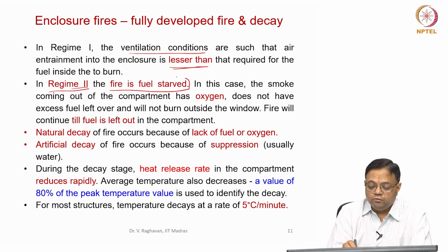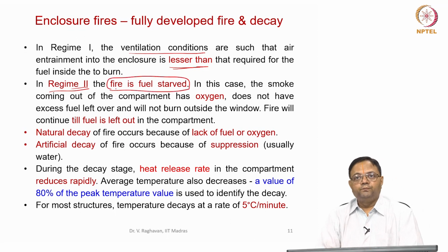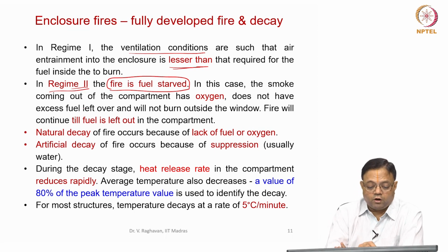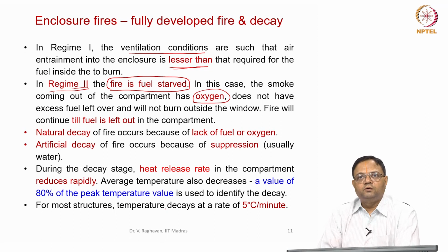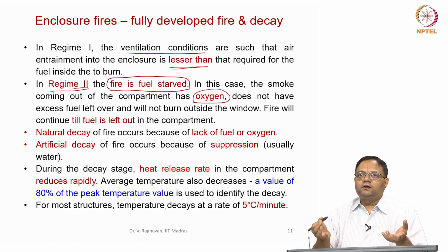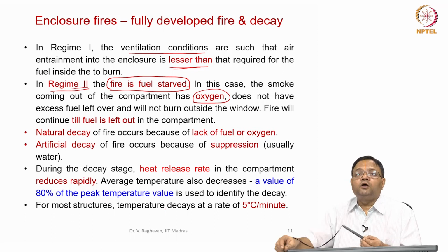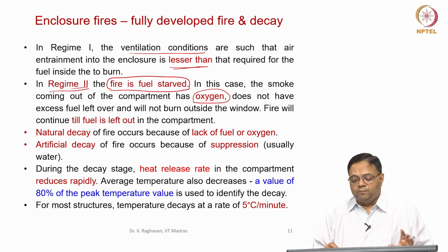Fire is fuel starved. Here, the smoke coming out of the compartment will have a good amount of oxygen. A lot of oxygen has entrained, but there is not much fuel, or all the fuel is burning within the compartment.